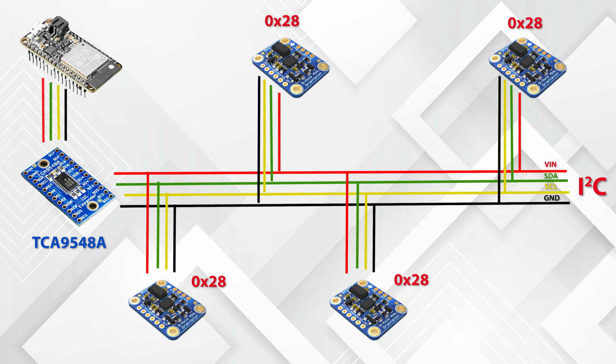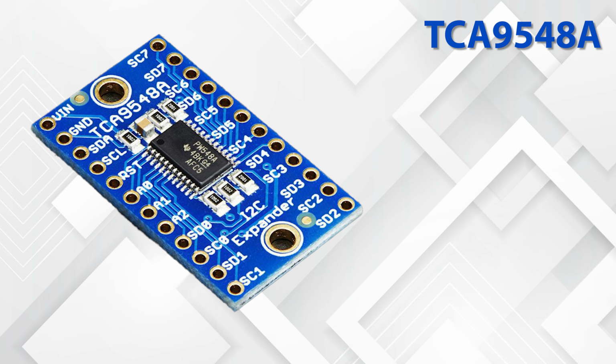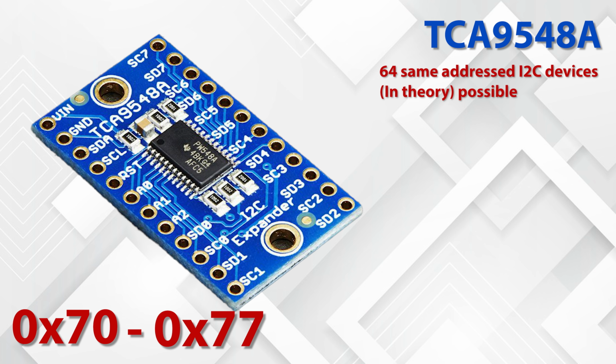It is a way to get up to 8 same address I2C devices hooked up on one microcontroller. This multiplexer acts as a gatekeeper, shuttling the commands to the selected set of I2C pins. Using it is fairly straightforward. The multiplexer itself is on I2C address 70, but can be adjusted from 70 to 77. And I simply write a single byte with the desired multiplexed output number to the port. Any future I2C packets will get sent to that port. In theory, I could have 8 of those multiplexers on each of the 70 to 77 addresses in order to control 64 of the same I2C address parts.